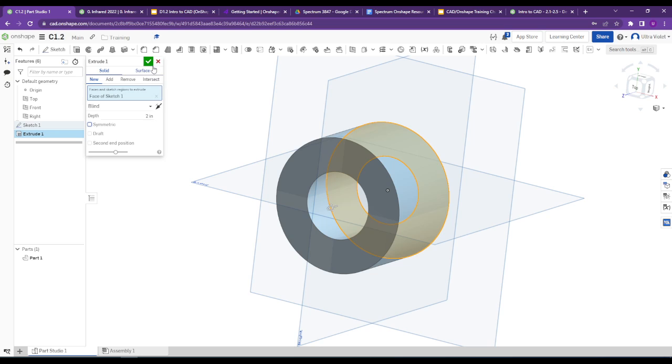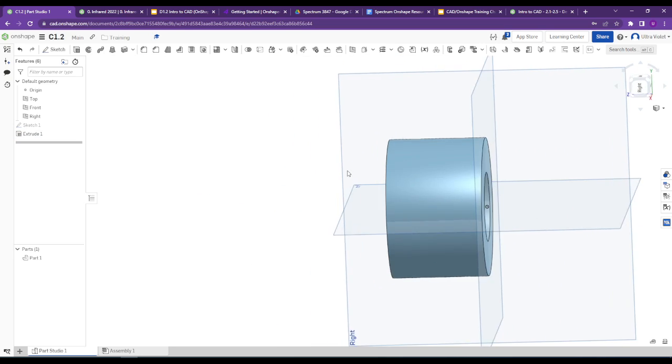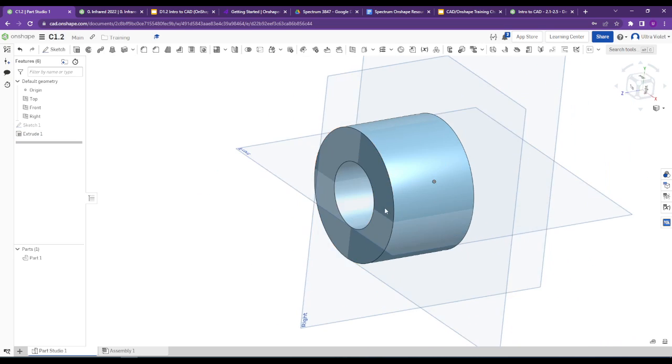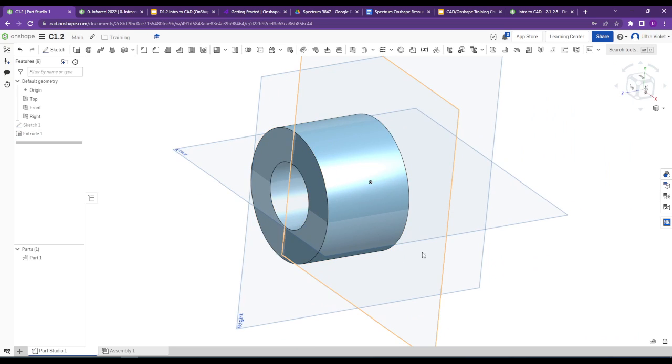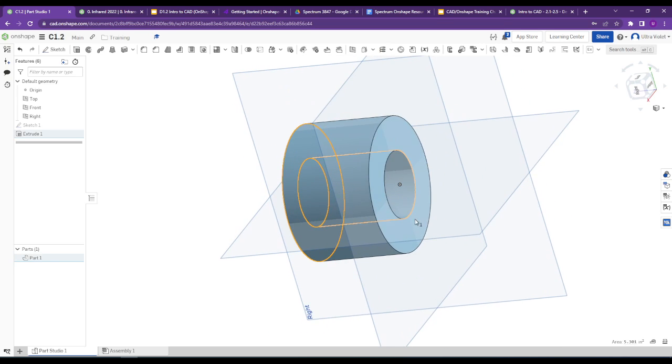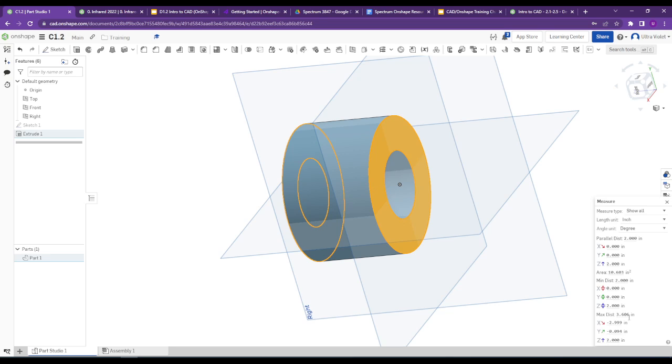And so that sets the exact thickness that this part is now. A couple very useful things that Onshape lets you do is measuring things is super easy in Onshape. If you just click on one face, if I want to know how far it is from this other one, if you just look down in the bottom right, you can see it says that it's already 2 inches. If you click the little measuring tool here, it gives you a lot more numbers. These ones are all basically the same because that face is always 2 inches.